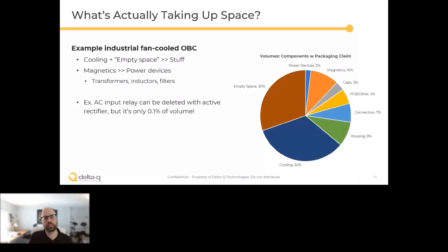Just because space is empty doesn't mean it's always not serving a purpose. Often we have to have certain creepages and clearances for safety and regulatory for live parts, or have shielding that sits between things to prevent crosstalk. But I've factored that in roughly into the packaging claim here.